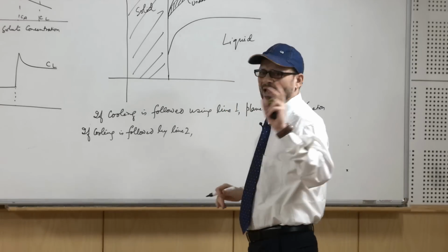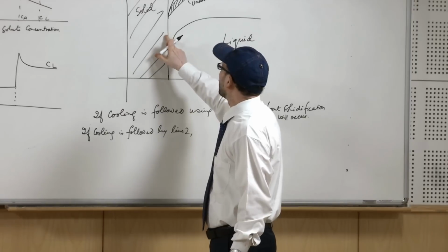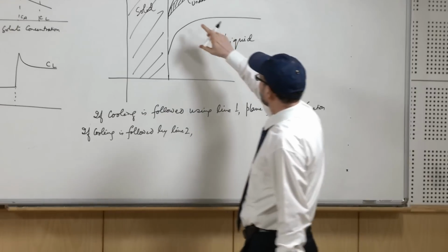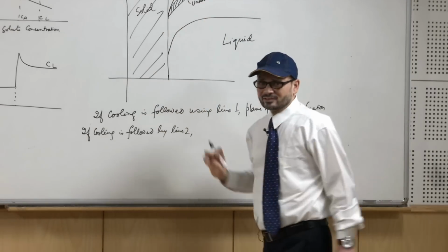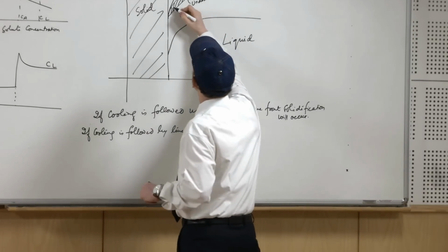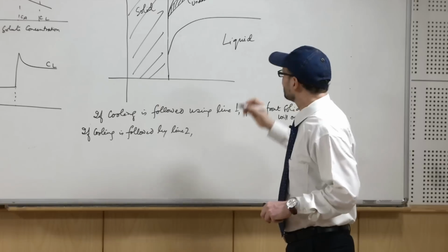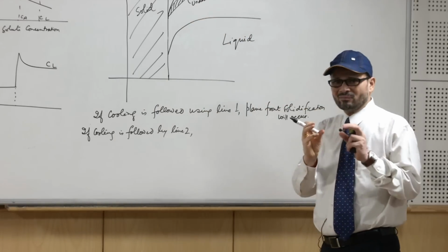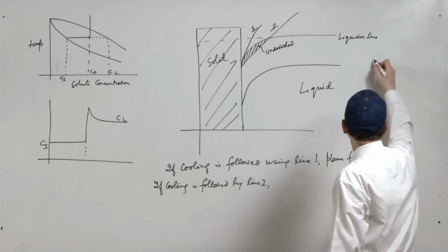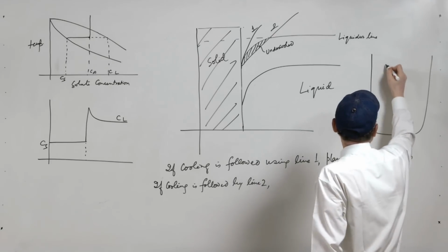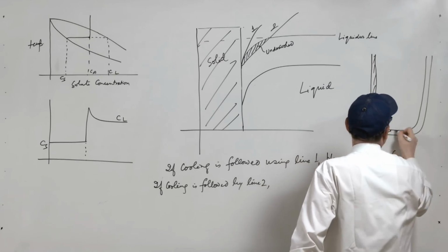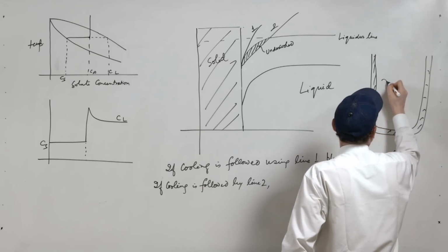Basically, in the ideal case of metals, your nucleation only has to start at this point or it has to go from here, but in this case, because of this concentration gradient and because of the existing cooling mechanism, a certain area becomes undercooled, and that will result in the formation of nuclei or solid phases in the zone somewhere. So, suppose some part has solidified, but in the zone somewhere something has formed.